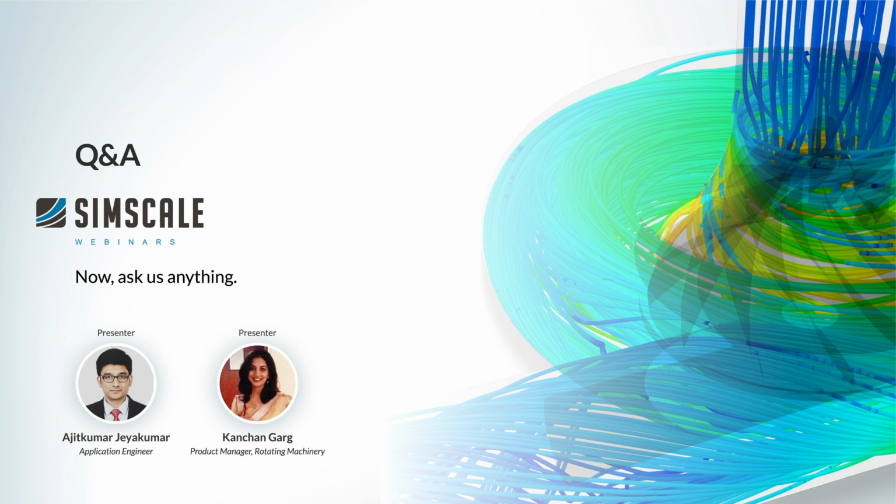What turbulence model does the subsonic solver use? Maybe I can take the question, Kanchan. So the subsonic module predominantly uses the K epsilon turbulence model, and it's well validated against a lot of measurement data where, as my colleague Kanchan mentioned, we are able to hit about 2 to 3% of experimental result accuracy.